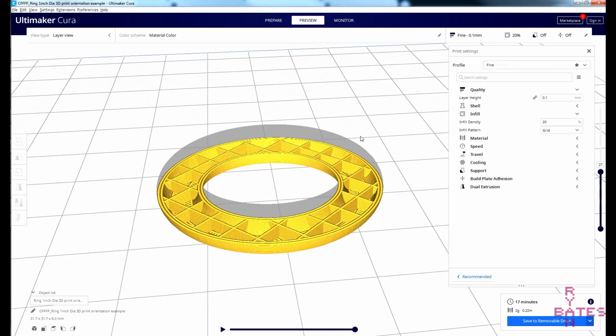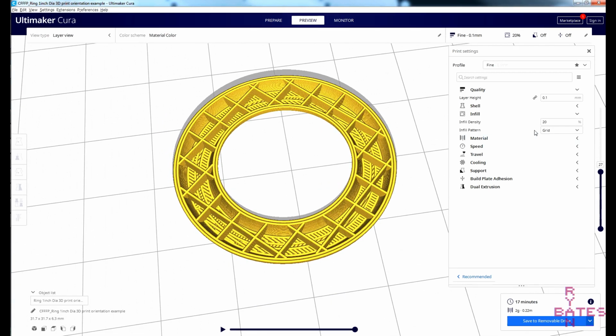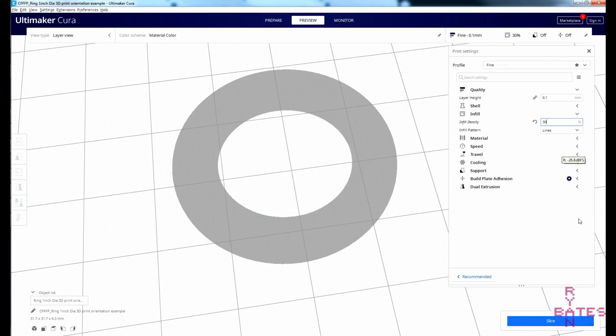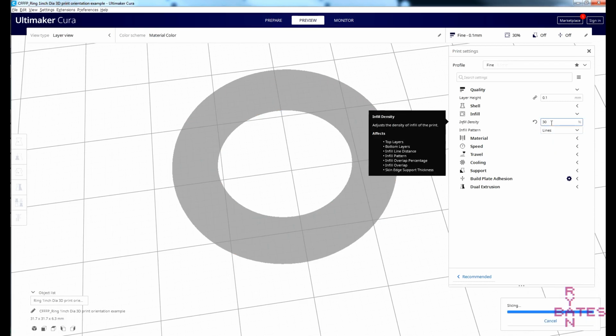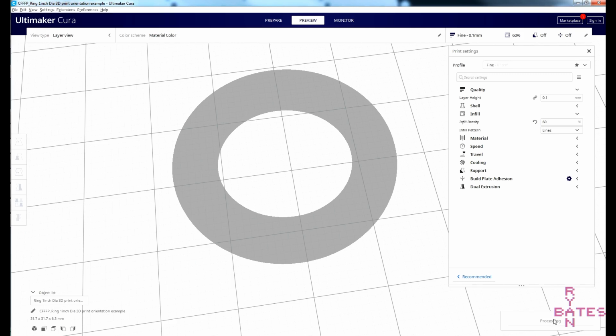The more infill, the longer the part takes to print and the more material that's consumed. Infill is the density across the entire part. Generally, a greater infill will improve the overall strength characteristics of your part. However, this benefit will start to plateau around 75% infill and up.